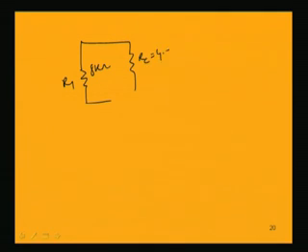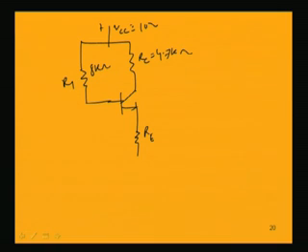So, in this circuit, the potential divider biasing scheme has the resistances R1 as 8K, RC is 4.7K, VCC is 10 volt, and this is an NPN transistor, and this resistance RE is 1.2 K and this R2 is 2 K. So, this is ground.